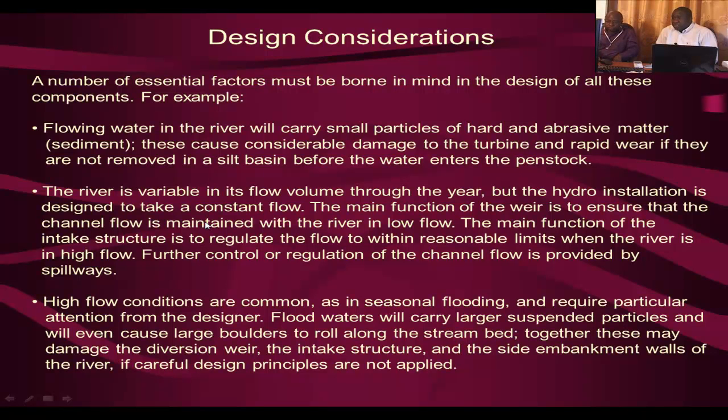to be removed. 2. The river is always in variable flow throughout the year, but the hydro installation is designed to take a constant flow. The main function of the intake structure will be to regulate the flow to within reasonable limits when the river is at its high flow.